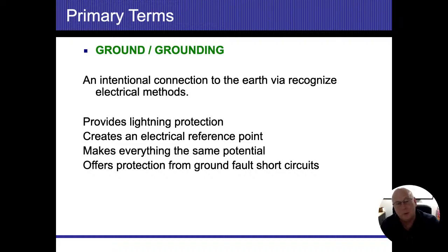So what I have to do is get that ground fault, because electricity is going into the earth when it's not supposed to. That's a ground fault. What I have to do is get that ground fault back onto the neutral, or the grounded conductor. If I can get it onto the neutral wire, now there's no resistance on that at all.